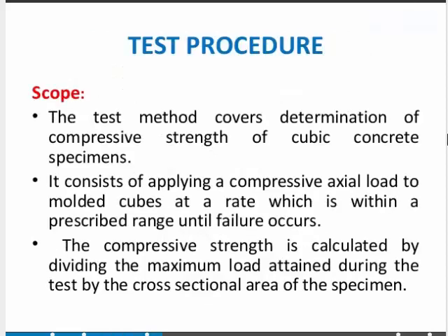The detailed test procedure is here, and I'll explain the whole procedure. Students, before the test procedure, the mixing of the concrete for the cube test is also important. It can be hand mixing, or mixing for sampling of the cubes for the test. Mix the cement and fine aggregates on a water-tight non-absorbent platform until the mixture is thoroughly blended and of uniform color.